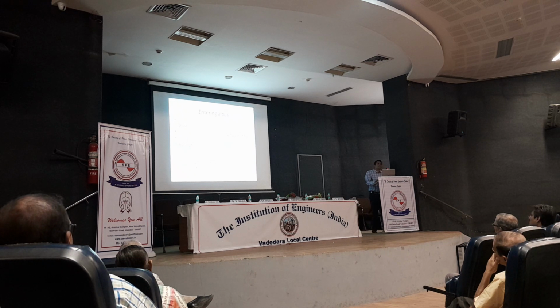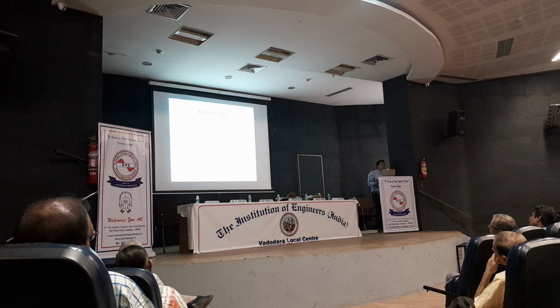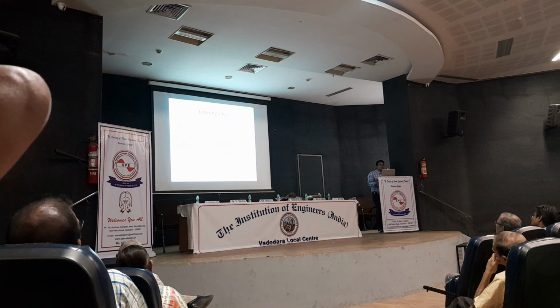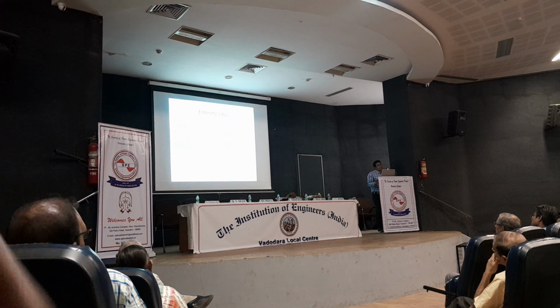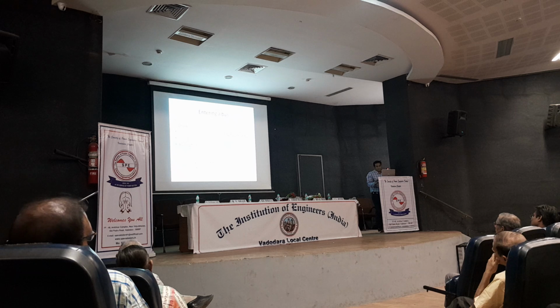For that we first select the bus in PowerWorld simulator. When we select the bus, we have to insert the bus information: the voltage ratings, bus number, and area number. That can be done once selecting a bus.